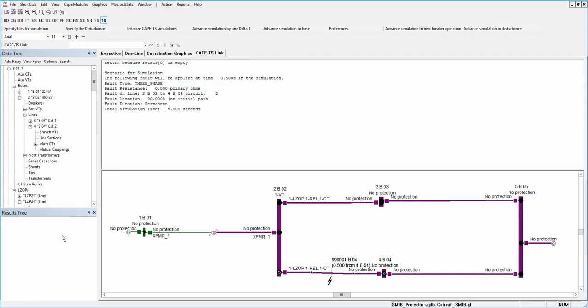You can see that there is a small window on the left side of the program, the results reader. Right now there aren't any variables here, so you should go to the macro and set tab and choose define set.